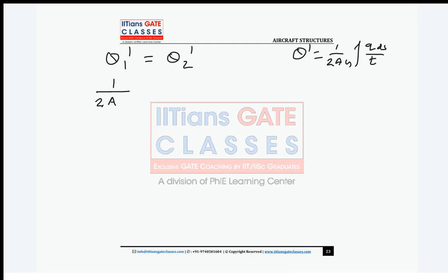So 1 upon 2A1, because area is different, G is same. Then integration q ds by t for cell 1. Now this is equal to 1 upon 2A2 G integration q ds upon t for cell 2.